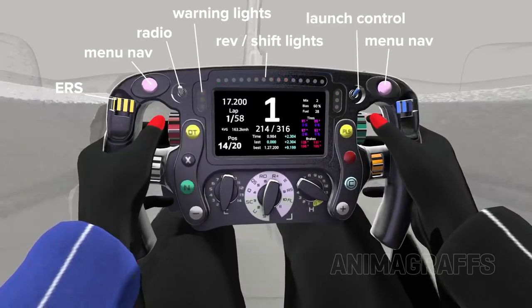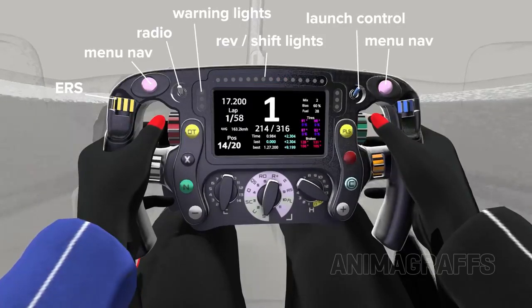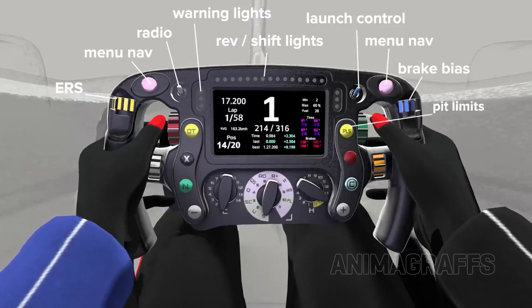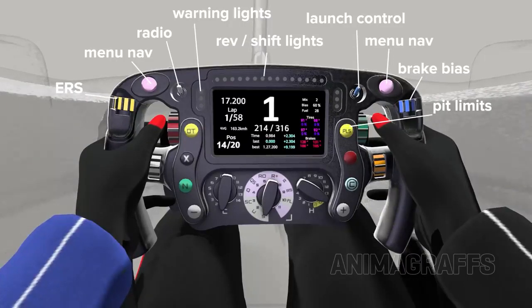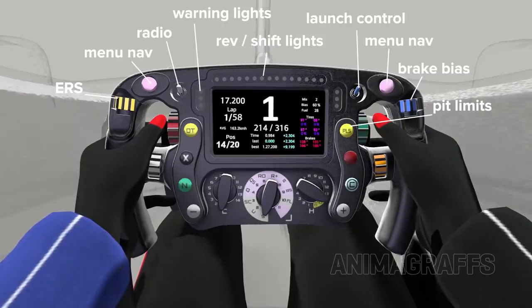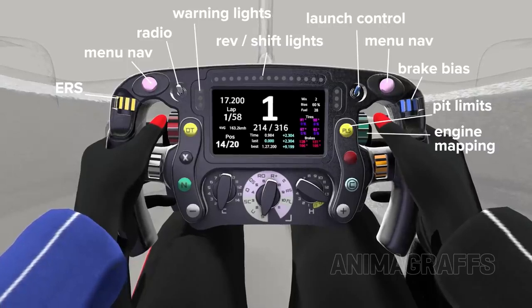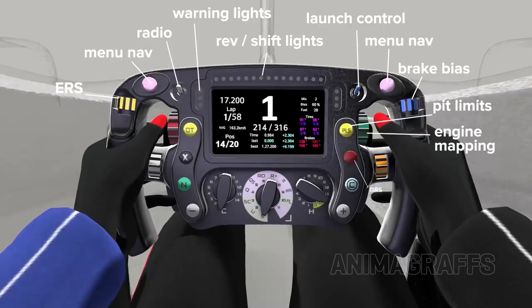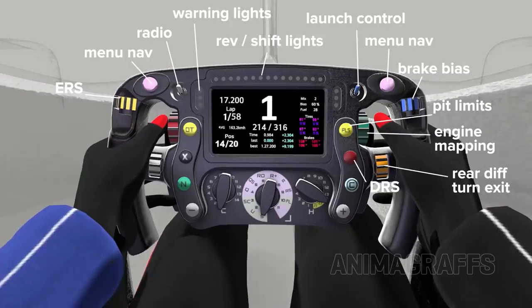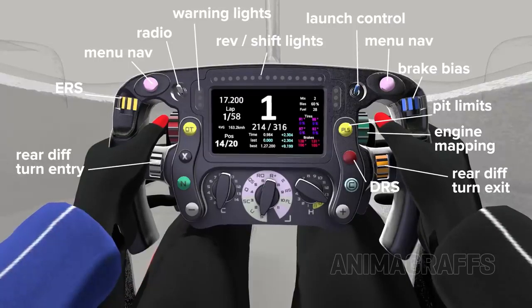The launch control switch, which is turned on for race starts and off when racing. The brake balance dial for front and rear brake bias. A pit limits button to automatically impose things like pit lane speed and acceleration restrictions. An engine mapping dial to alter engine performance characteristics. DRS toggle button. Rear differential lock open or closed adjustment with separate turn entry and turn exit adjusters.